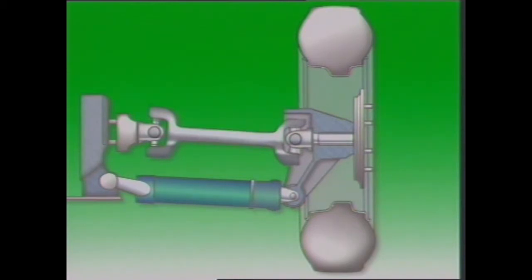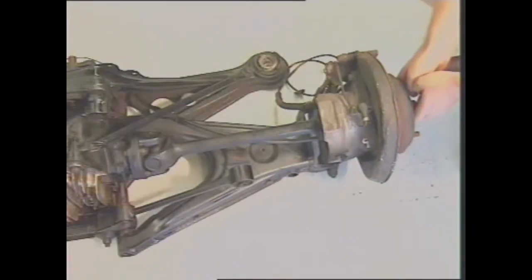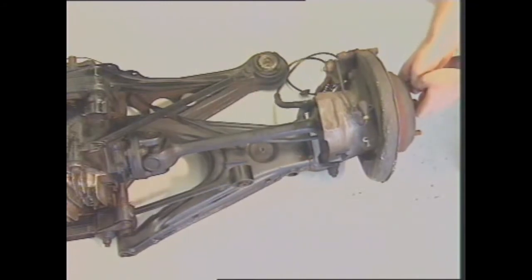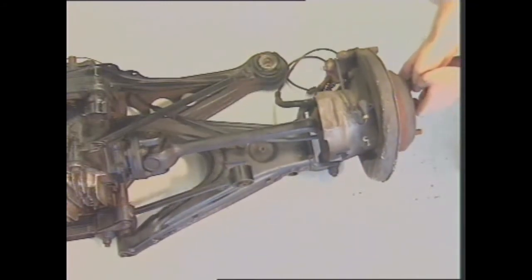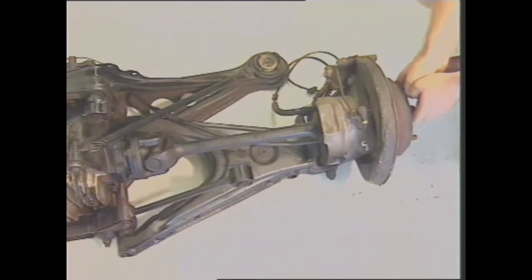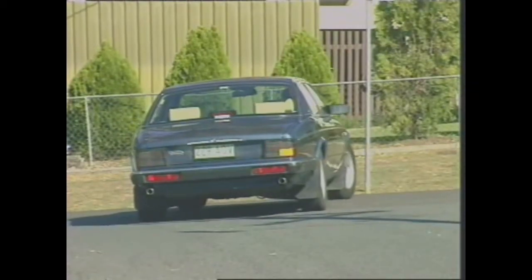However, the drive shaft itself can be used as the upper link of the suspension, providing the pivot point. The splined section is unnecessary, and the shaft can be made as one piece. As with the front suspension, the lower link has widely spaced pivots to provide stability, and the unequal length links maintain the track nearly constant, although with deflection, some camber change does occur.